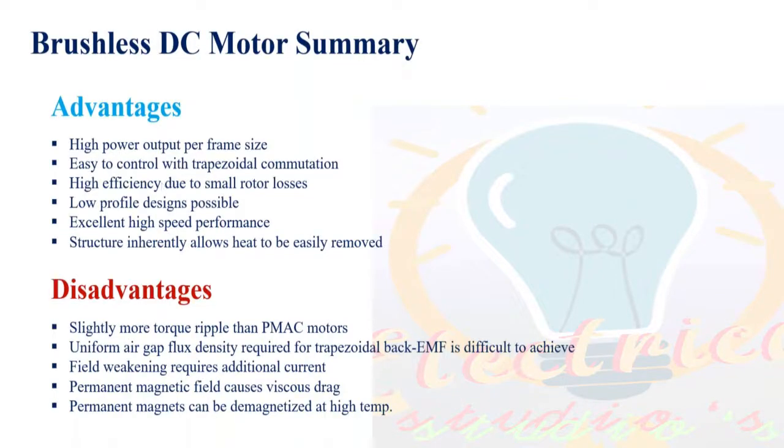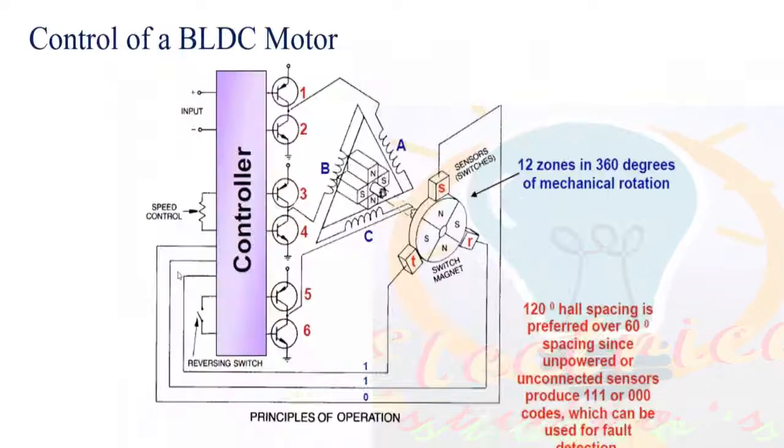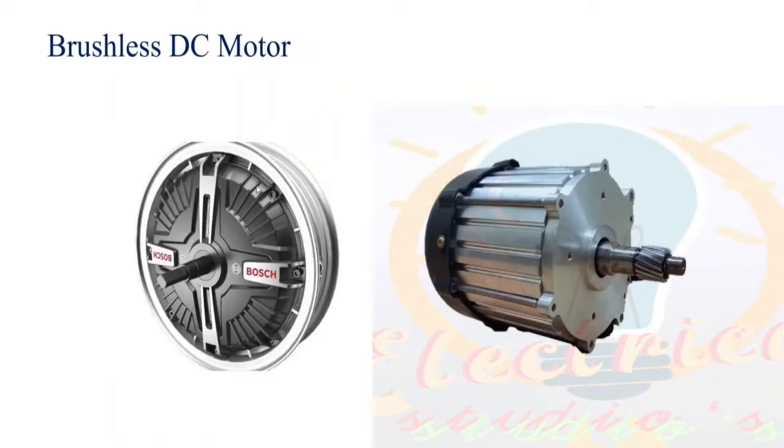Efficiency is quite good. And especially the cooling system, in case of BLDCs, they have the tendency to cool very easily compared to the PMSM motor. Through convection itself, they can cool very easily. But in terms of hub motors, temperature issues are there more. That is also one reason people go for